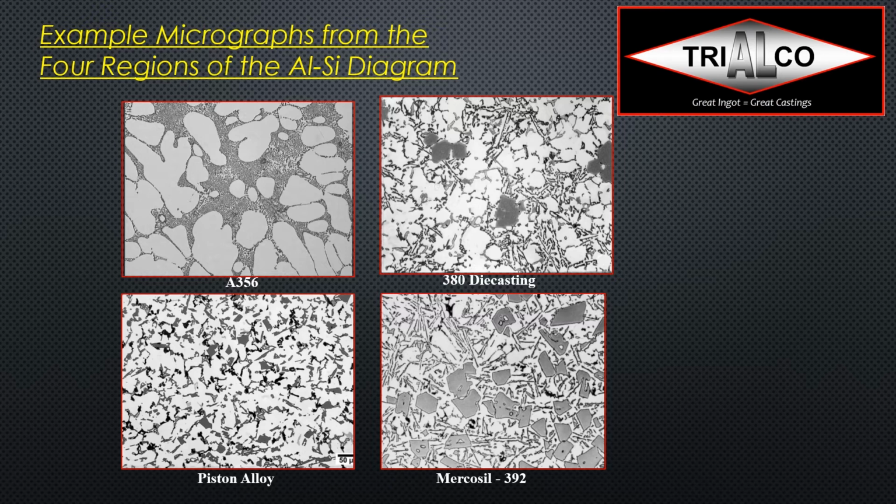If we look to the right, A380 die casting, we can see there are big intermetallics. We can see there are iron needles. There are a lot of things that will definitely block if we pull this alloy, and therefore that's where cracks will easily initiate, and that's why we will not get much of an elongation out of this alloy. On the left bottom we see a piston alloy, and we certainly don't want high elongation in pistons. There we want high temperature stability, so very important.